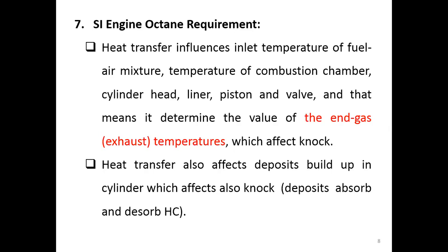And this will affect the NOx, because if you have heat transfer out, less NOx might happen. But if you have less heat transfer out, you keep much of the heat in here. If it's too much, your engine can knock because of that much heat.